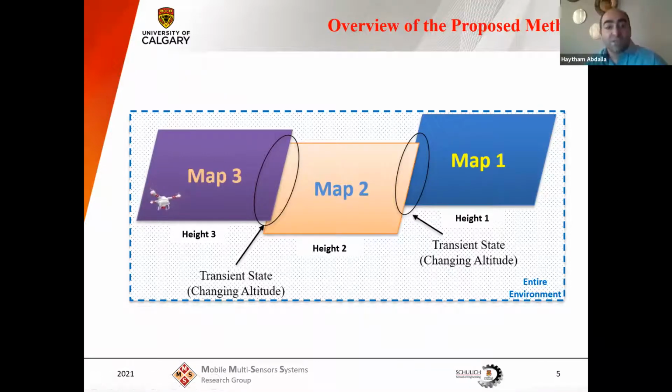This splitting process aims at reducing the memory consumption and processing costs of the entire constructed map, and also avoiding restrictions for assigning grid size before the flight like other methods. Moreover, for more memory reduction, the proposed method retains the executed trajectory for backward return, instead of building another 2D map slices during the exit process.